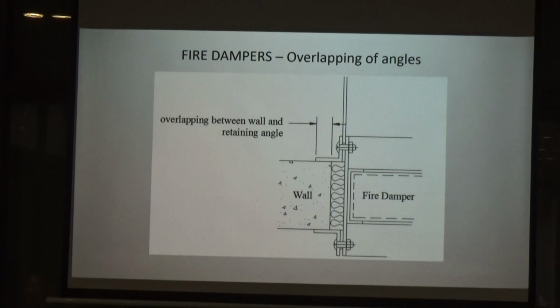Actually they can calculate the minimum size. If I give them the wrong maximum size, then my retaining angle cannot cover the hole, and we have a problem. So we just give them the minimum size, because with the 10 mm we actually give extra already. But do you think it's our responsibility to tell them what is the maximum opening? They might open too much, and then you can't get something like this. Whether it's our responsibility to advise them.